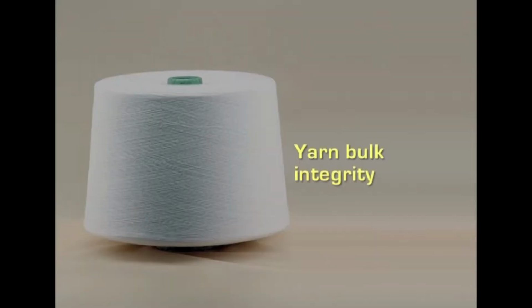The more number of fibers in a square inch would lead to a higher density. So, ring spun yarns would have a higher density of compactness even than the rotor spun yarns. The next characteristic of the yarn would be the yarn bulk integrity. It is nothing but the fiber arrangement in the yarn structure. Even here the type of spinning would influence the bulk integrity or the fiber arrangement. So, you can make a yarn in such a way that it is lively enough, and it would also influence the dimensional stability, the yarn appearance, the yarn strength and the fabric cover.